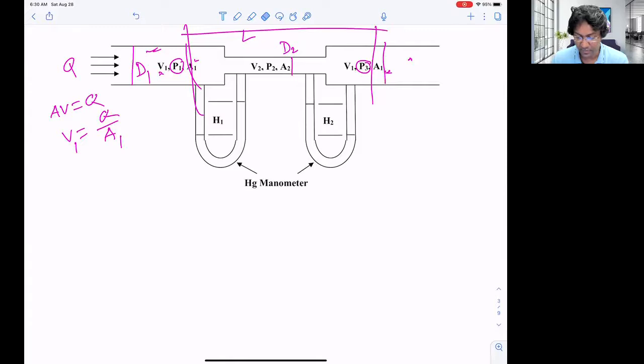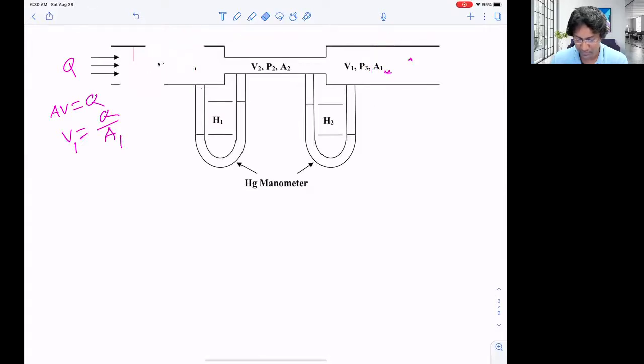So here we are only considering minor losses. That's why the section of the pipe, the length of the total experiment, is not that long, so that we can omit the major loss. We are focusing only on the minor losses. So we can write the experiment, because we know there it will be contraction, and there it will be expansion, and here we'll have eddies or vortices, right?